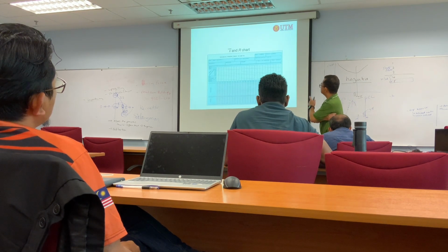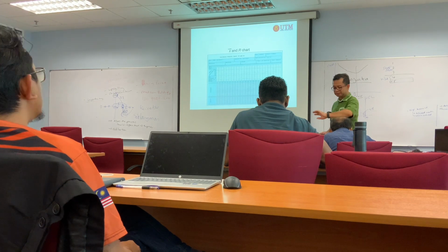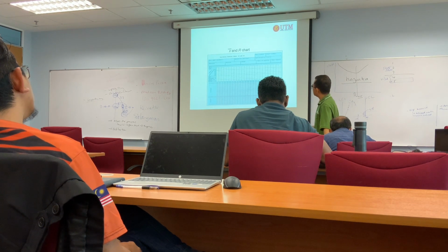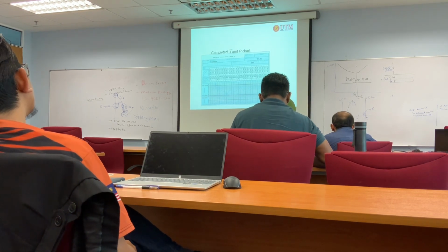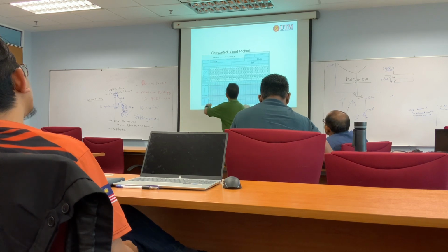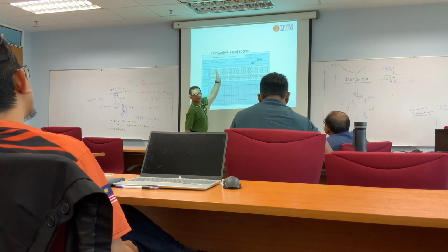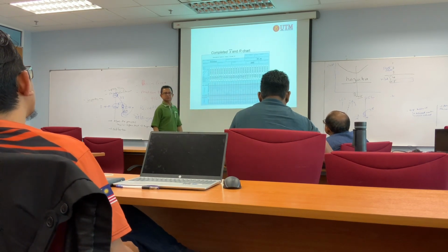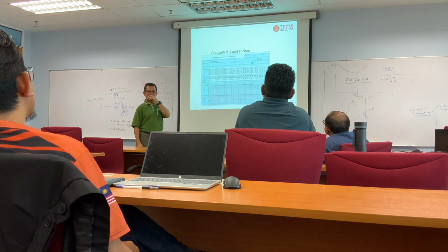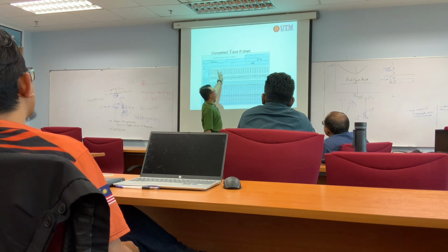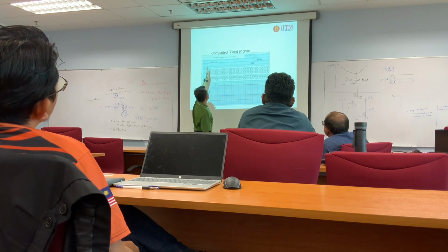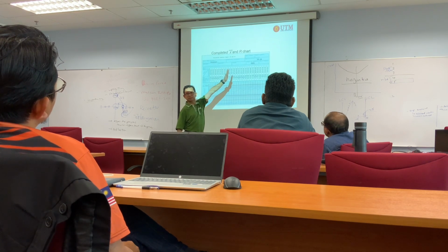This is just an example X bar R chart. So what we want to do is we have the data like this. Each sample measurement we call a subgroup. Let's remain standardized as subgroup, because this will be the population and this is a subgroup each time we collect the data.